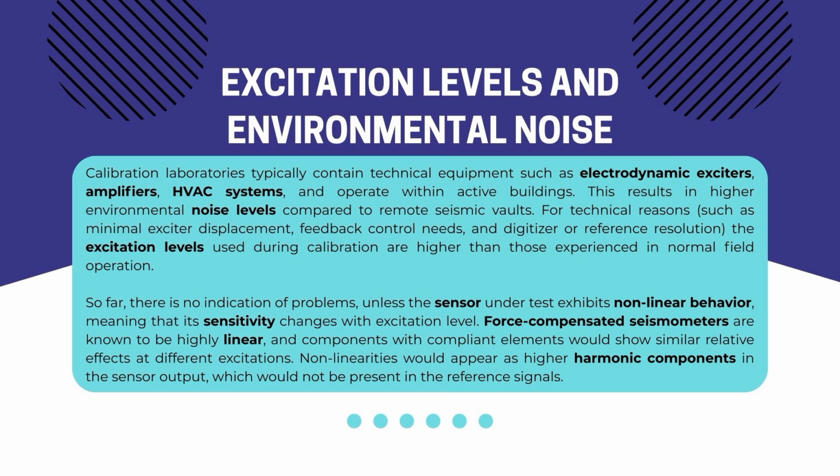So far, there is no indication of problems unless the sensor under test exhibits nonlinear behavior, meaning that its sensitivity changes with excitation level. Force-compensated seismometers are known to be highly linear, and a sensor with a compliant element would show a similar relative effect at different excitations. Non-linearities would appear as higher harmonic components in the sensor output, which would not be present in the reference signals.